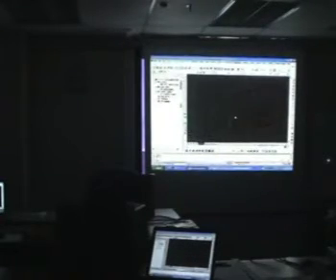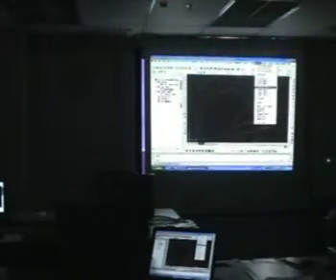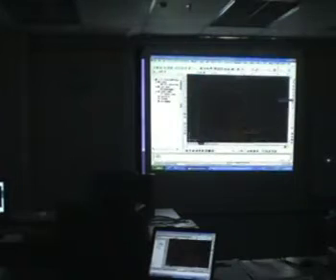And another problem with these contours is that you find there's no text whatsoever. You have no idea what each contour level is at. You can use the contour labels. I'm going to use group interior, and I'm just going to draw a line right through. When you zoom in, you can see the text. The text can also be adjusted.